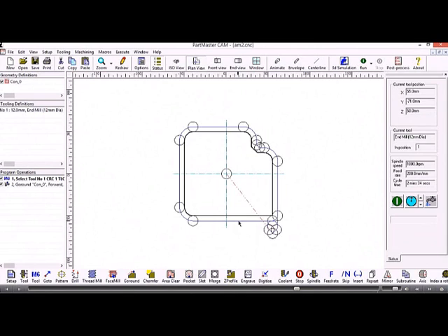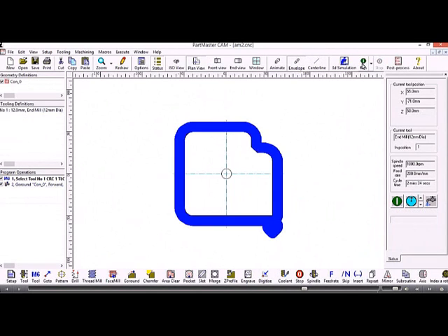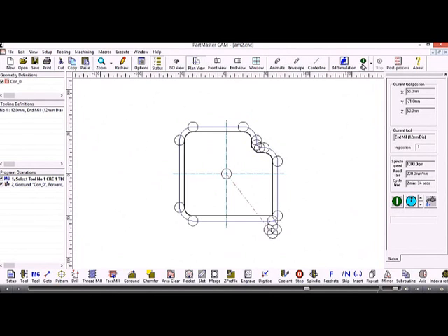So that's looking at it in the plan view. If I want to view just the tool center line, I click center line and run the job. That just shows me the center line of the tool. The tool envelope will block out the tool so I can see the tool diameter. Switching off all of those options just gives me the tool diameter and the center line.